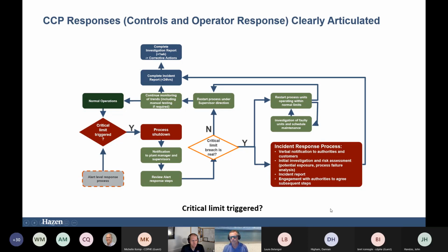And that's effectively what we had in place. The other thing that I didn't mention here and should have is that one of the really useful things that I found operationally was on our SCADA screen or our HMI screen was that the default screen at each of these plants was just a list of squares with each one of the critical control points and a condition. Green, yellow, red.